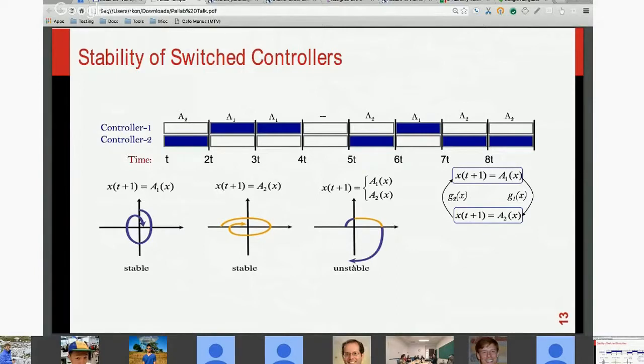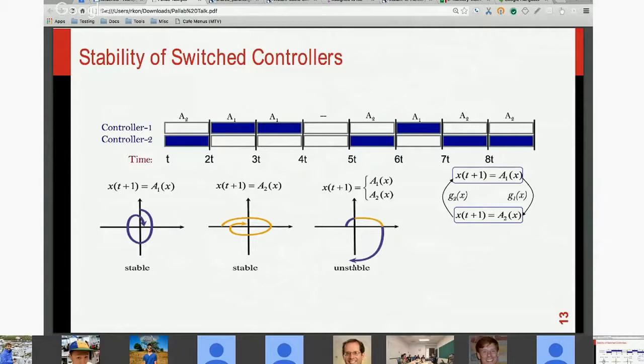ability to arrive at the proper position is problematic, because of the time it takes between when you implement your action, that is, you move the knob, and when the right temperature water comes. There is a gap between the two. Why? Because there is this pipe, there is a length, there is a delay for the water to flow through the pipe and then to your body, right? So this delay aspect is something which can completely mess up a control system. And the delay typically will come from the execution side. That is, from the scheduling perspective, if I don't schedule the task on time and I get delayed, then a stable controller can become unstable because of this, right?